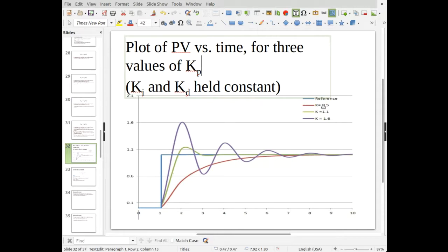And then of course, if we decrease K all the way down to 1/2, we're basically taking energy out of the system, or out of the control piece anyhow, and it's given us an overdamped response. Now notice over here, this isn't a perfectly smooth line. It looks a little awkward here.